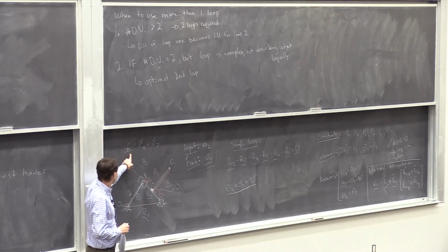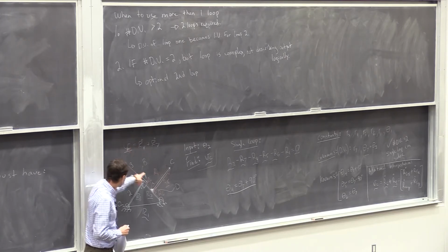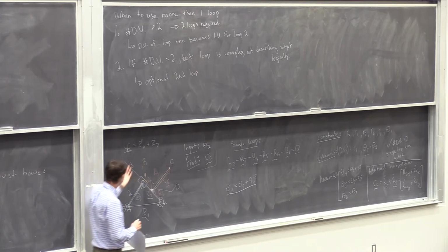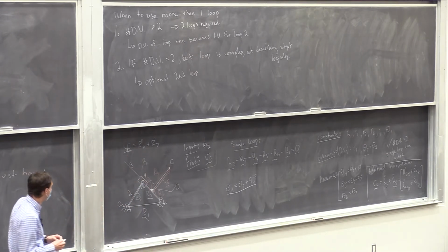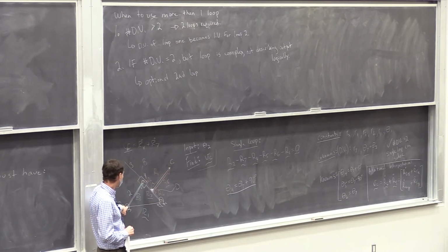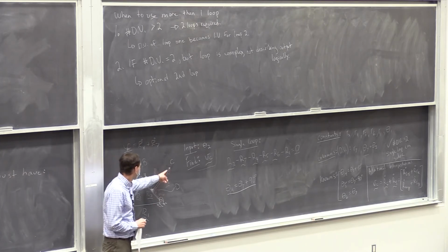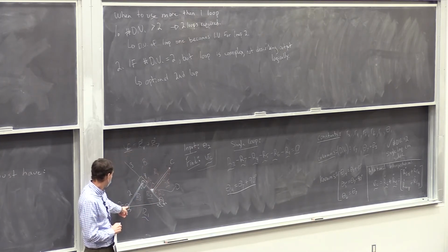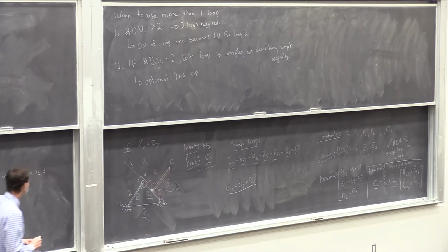This is like converting into velocity polygon language. B relative to C, it's a vector from C to B. So you could use that to check your work from multiple methods. Another way you could do it is starting at this point, 2 minus 7 plus 4. That would get you velocity of C relative to this point.